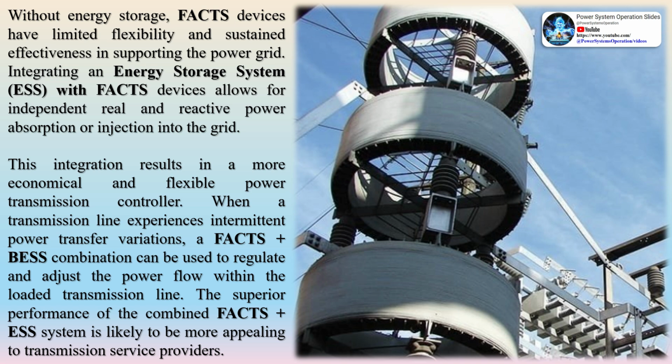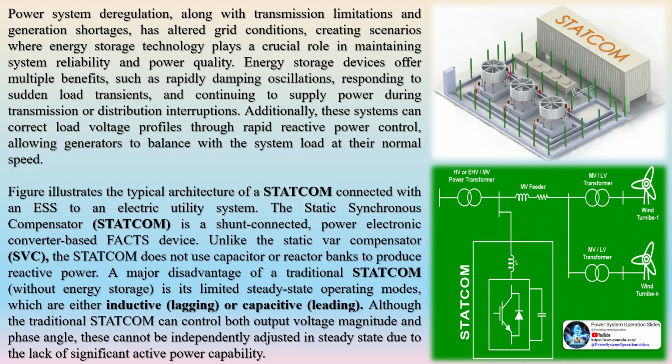STATCOMs with energy storage offer numerous advantages for power system operation and control. These applications include reactive and active power control, stability enhancement, system security improvement, integration of renewable generation, avoiding new transmission line construction, managing power flow congestion, and providing control mechanisms for remedial action schemes.